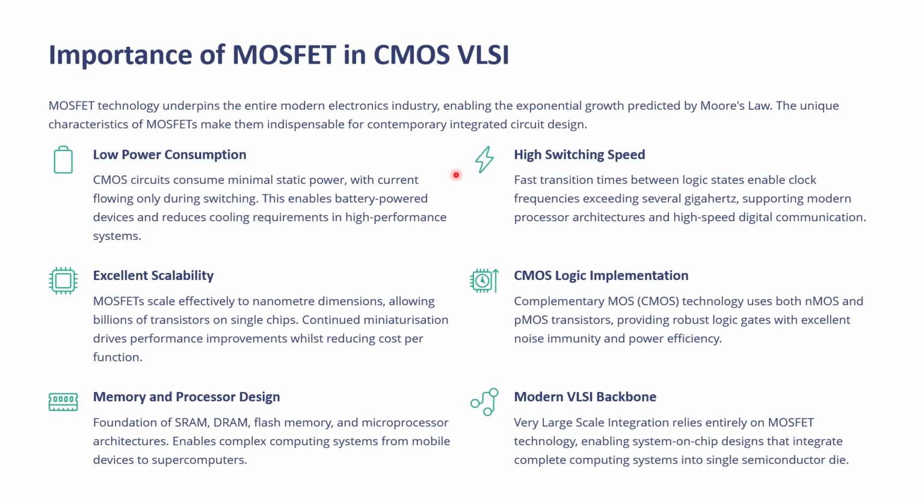MOSFET technology underpins the entire modern electronics industry, enabling the exponential growth predicted by Moore's law. The unique characteristics of MOSFETs make them indispensable for contemporary integrated circuit design. Low power consumption: CMOS circuits consume minimal static power, with current flowing only during switching. This enables battery powered devices and reduces cooling requirements in high performance systems.